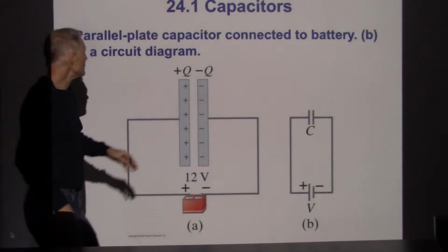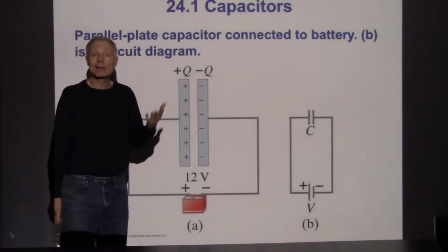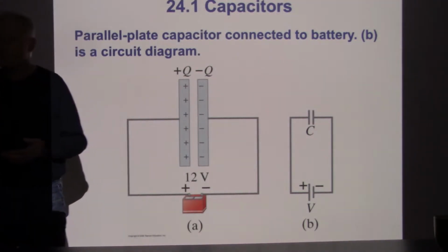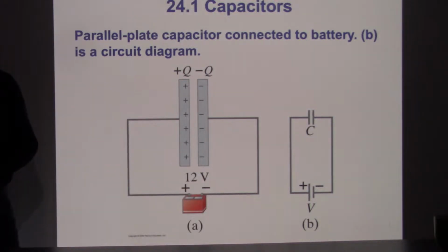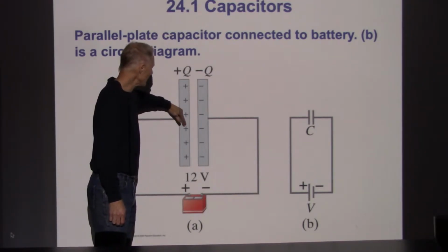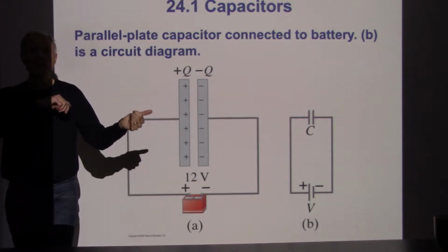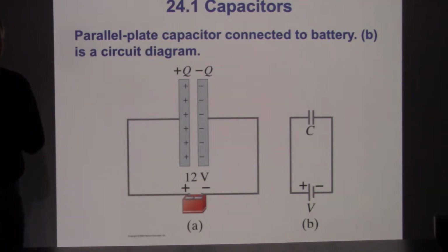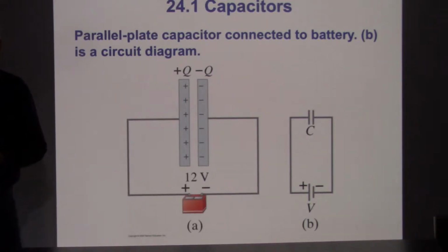Now you might say, because the negative charge buildup and the positive charge buildup are the same amount, the capacitor overall remains electrically neutral also. Yeah, that's true. But because we've got negative charge isolated from the positive charge, we're able to add to that negative charge or pull some of that negative charge out. So it does become a charge reservoir for the rest of the circuit.